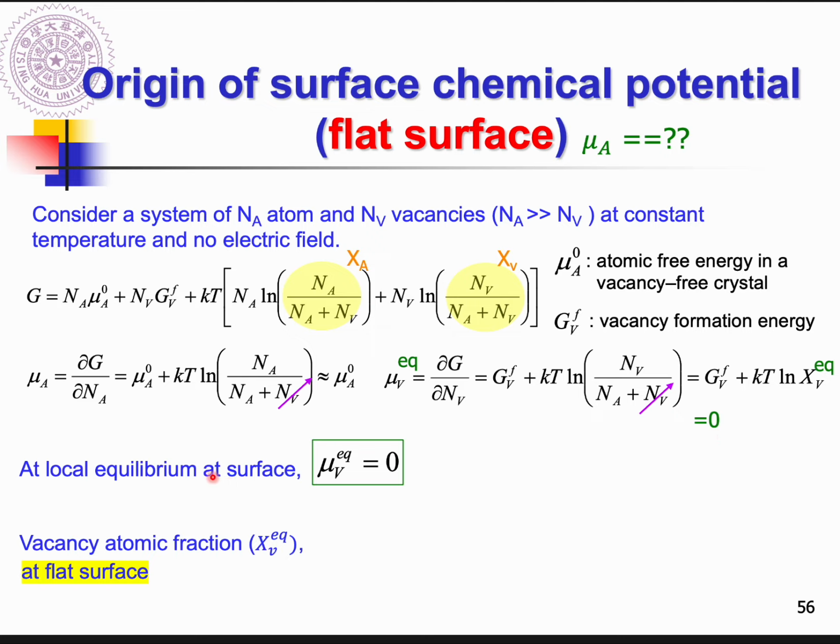The reason for this assumption is that, as you know, we don't really have a vacancy flux on the surface or inside our materials, right? Because the vacancies are always trapped in crystal imperfection sites, so we cannot really visualize the vacancy flux flowing through our materials. Vacancies are trapped in crystal imperfection sites, including dislocations, grain boundaries, and so on. Under this situation, we also can assume there's no flux, right?